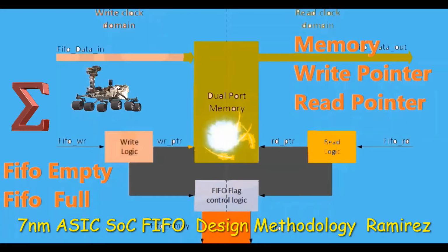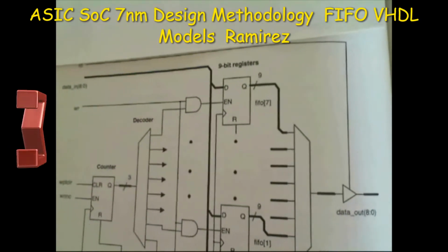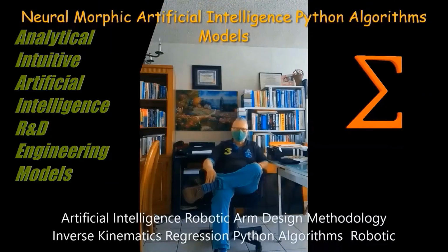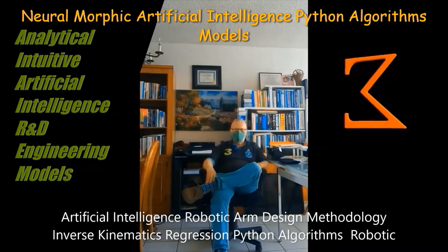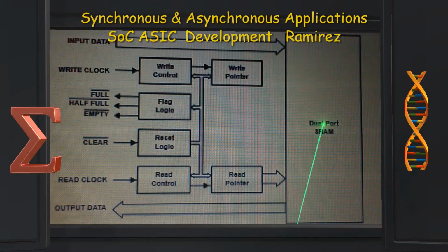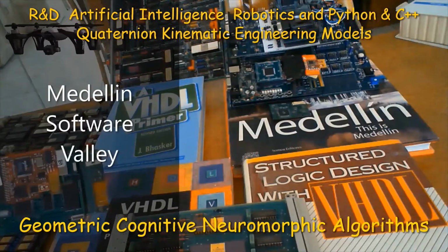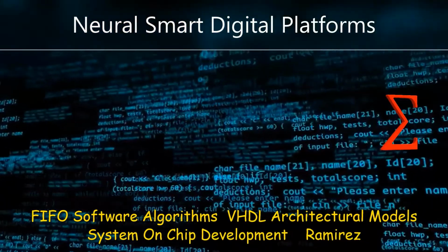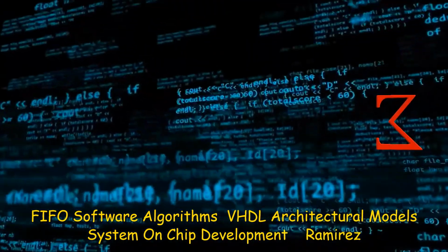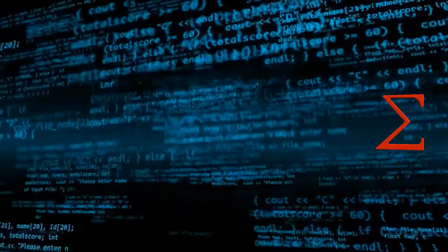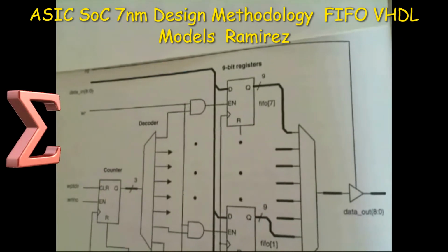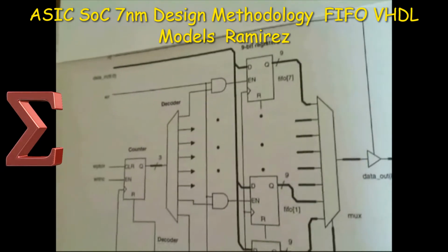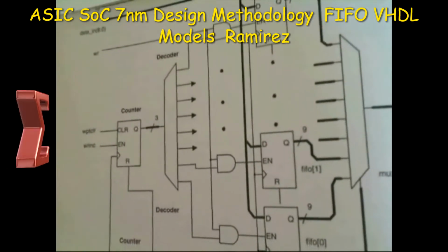So in order to write data into the FIFO, first push the data onto the data in bus and then strobe the write enable input high for 1 clock cycle. This will write whatever is in the data in into the FIFO's internal memory. For writing in bulk, the write enable signal can be left high while changing the data on the data in bus each clock cycle.